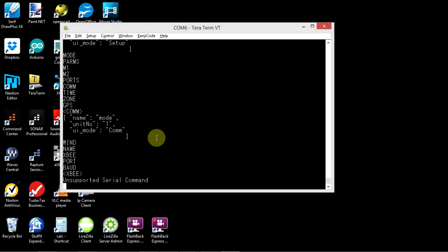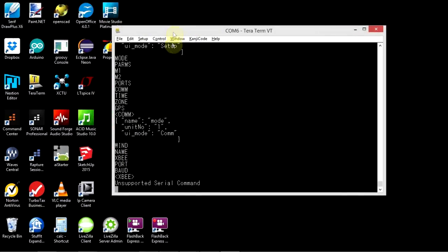You have to do that at the Mega Tracker itself. So when you select XBee on the Mega Tracker, it'll ask you the unit number as well as the XBee channel and address settings. But at this point, we recommend using the XCTU configuration utility for setting those values rather than the Mega controller, because it could be a little bit confusing.